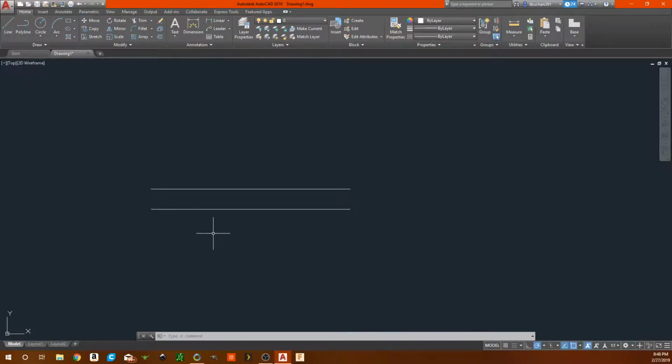Now what I'm going to go over next is drawing a line at an angle. You can either pull it up like this and you see the angles coming out, but like with the other one, there's an easier way to do it. If you just press shift 2 for the @ symbol, you do however long you want it to be.